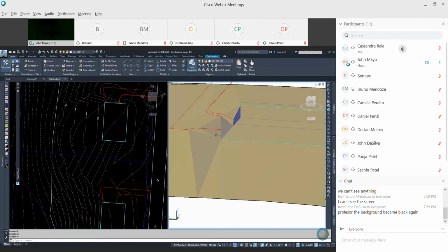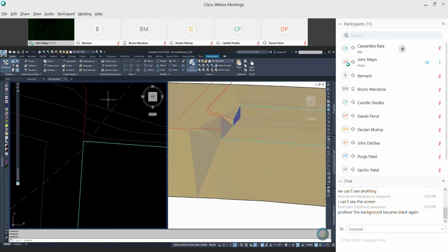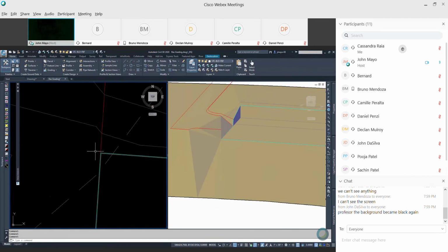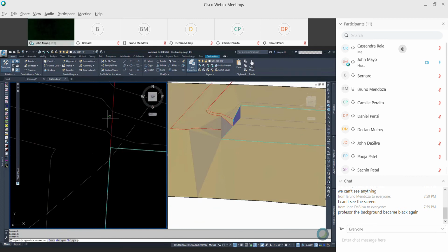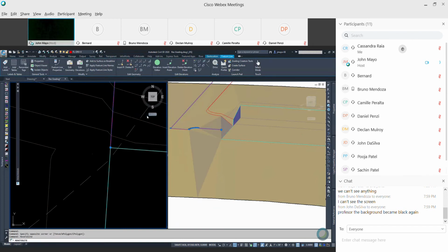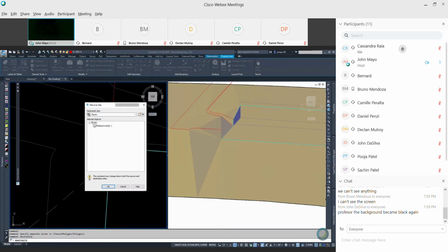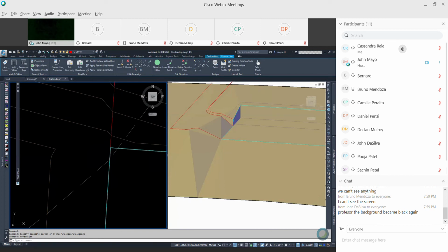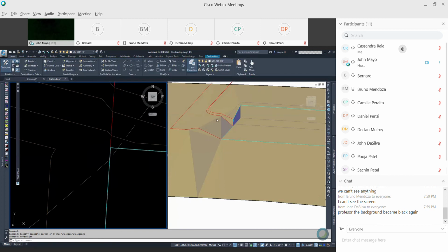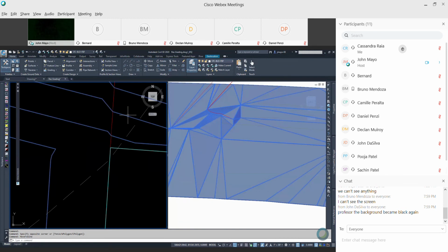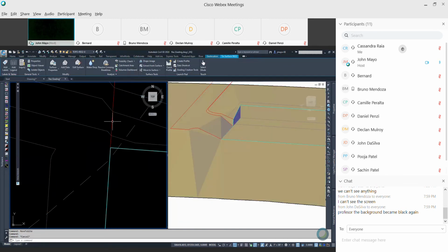Look at this. This is either not on the same site or I did not hit that elevation correctly. Let's see. Right click, move to site. And I know it's not, look at that, it's still on the driveway site. I know it wasn't on the same site because there cannot be 2 different Z values at any point. So I move this to here, and look at that. The feature line automatically finds the elevation. All right, so I'm working through that. Let's look at my driveway.